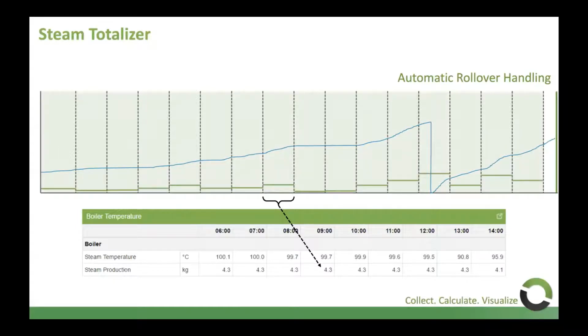Now, very importantly, and we'll discuss it a little bit later, we also need to know, obviously, when there was a rollover that occurred in that totalizer value, so when it resets to 0, and we need to be able to cater for that when we do these different aggregation techniques. So again, that one result will be stored inside of the Flow ODS database. That's then presented either on the dashboard or pushed out to another system.